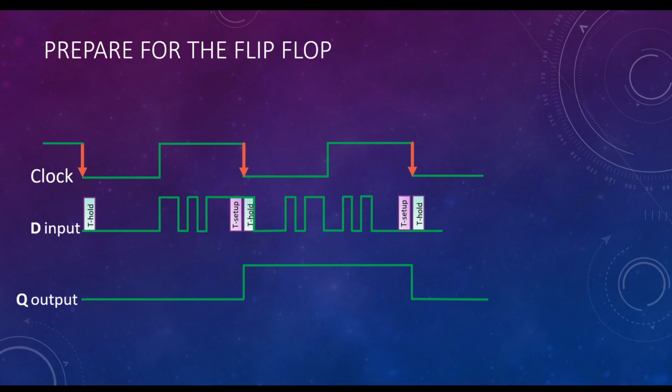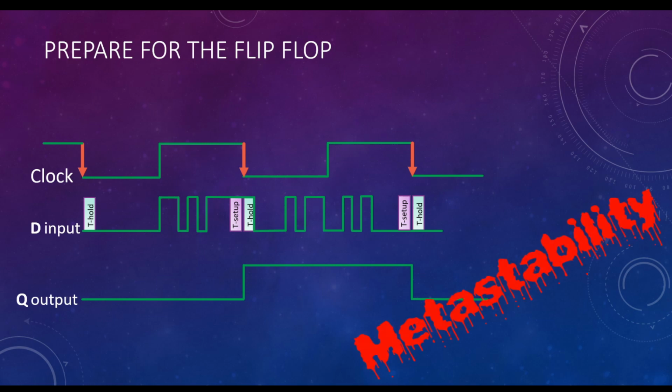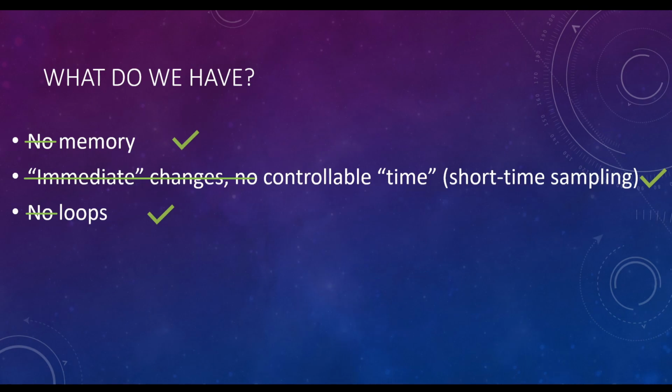If you neglect T setup and T hold, you may get something called metastability. Metastability is bad and can mess up things for you very badly. It is outside of the scope of this particular video, but I do intend to address it in future videos.